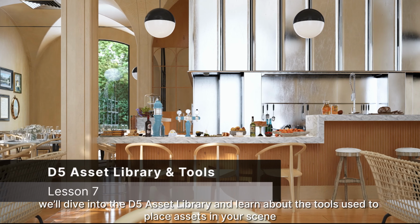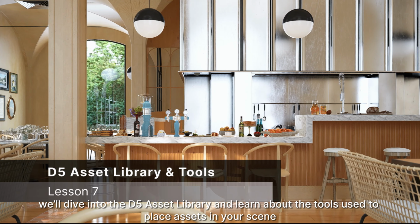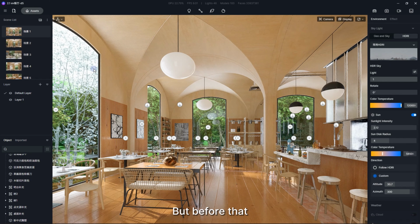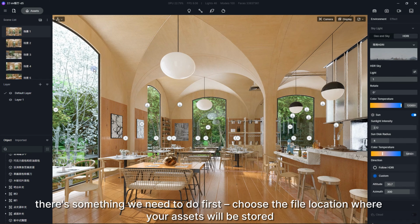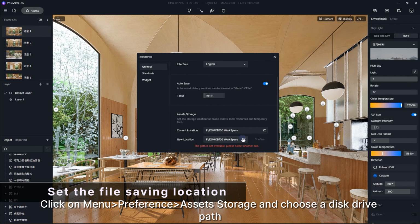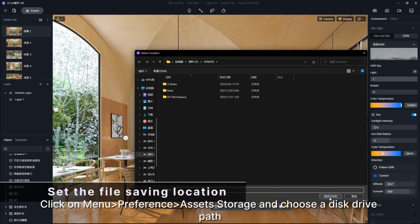In this lesson, we'll dive into the D5 Asset Library and learn about the tools used to place assets in your scene. But before that, there's something we need to do first: choose the file location where your assets will be stored. Click on Menu, Preference, and then Asset Storage and choose a disk drive path.